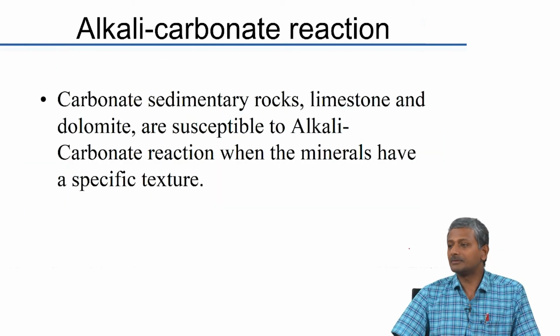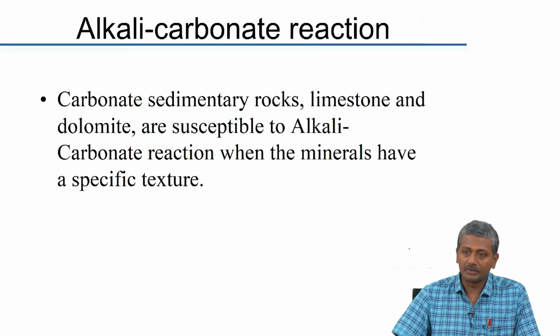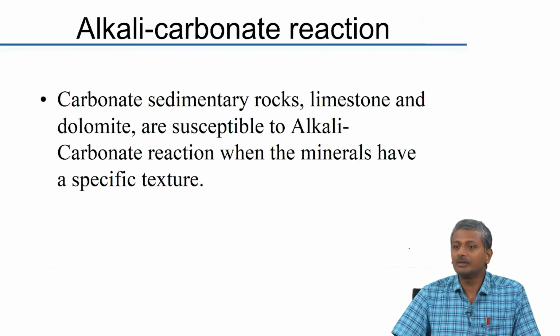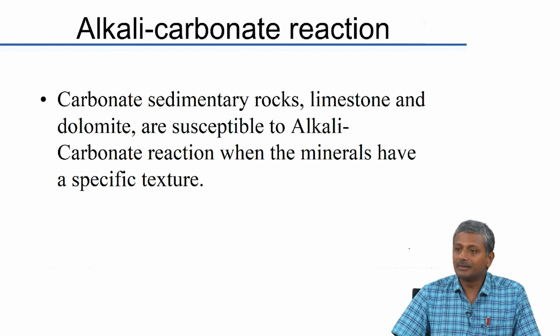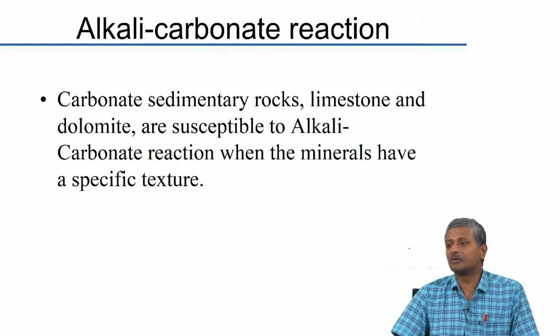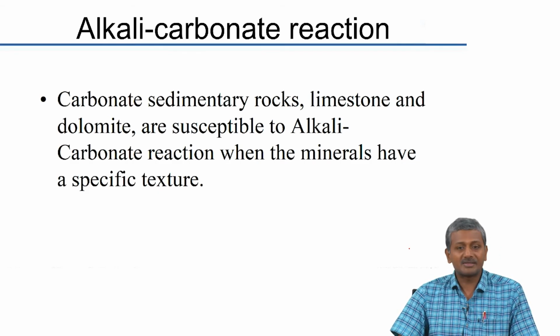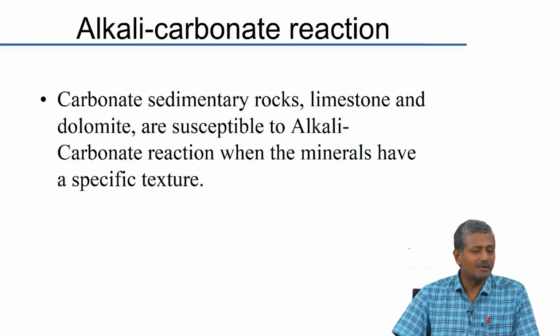Now, sometimes this alkali silica reaction could have a carbonate counterpart in alkali-carbonate reaction. This is a reaction which happens when you have carbonate rocks like limestone and dolomite, which could react especially when they have a very large amount of clay bearing minerals. Now, this is a little bit of a difficult problem to understand because the reactions are not very well understood in terms of how they actually lead to expansion and formation of cracking in concrete.